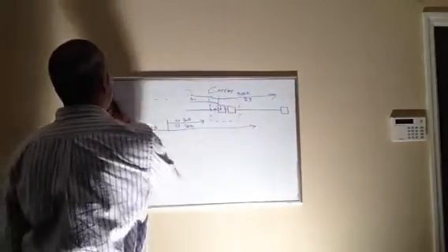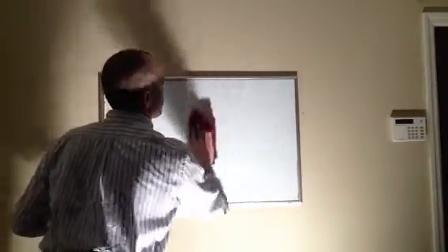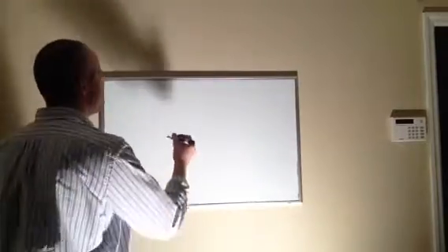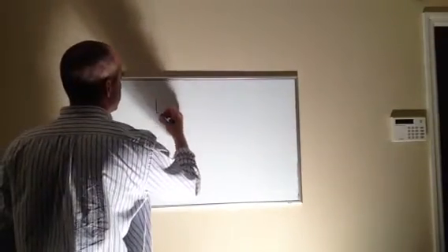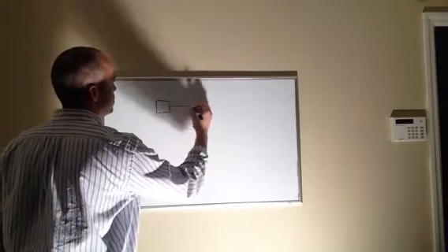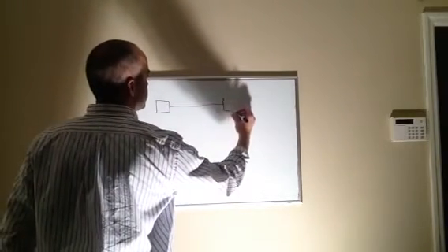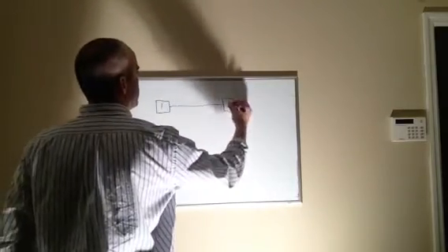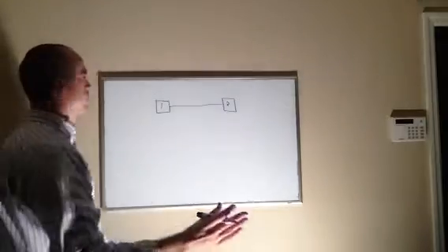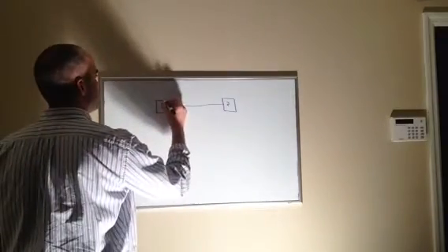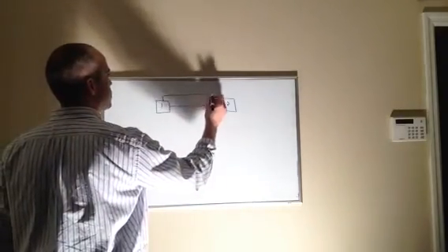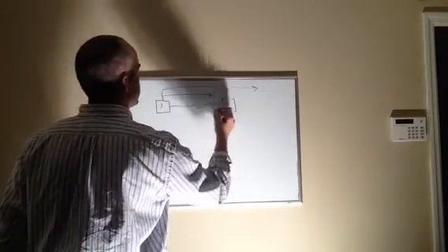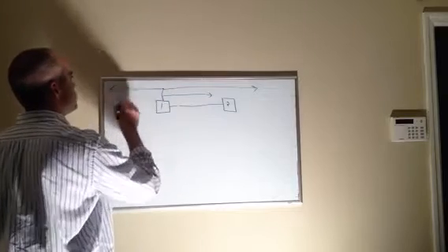Now, let's take a look at POTT. Same principle, just a little bit different in operation. We're going to make this just a little more simple on the board here, not jumble it up as much. Okay, we got breaker 1, breaker 2. Very same principle. Zone 1, 90%. Zone 2, 120%. Zone 3, reverse looking 300%.